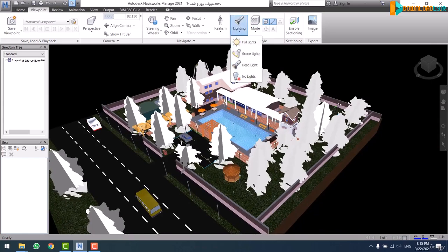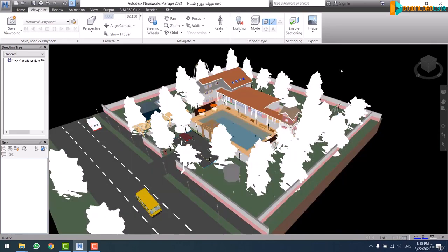But about lighting, here as you can see we got 4 options, and right now if I choose no lights, this option uses no lights. All geometry is rendered with flat color. Check this out. As you can see in the scene, lights are removed, and this mode switches off all lights and the scene is shaded with flat rendering, and the dimensions are hard to be recognized.